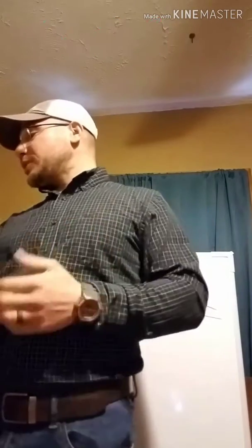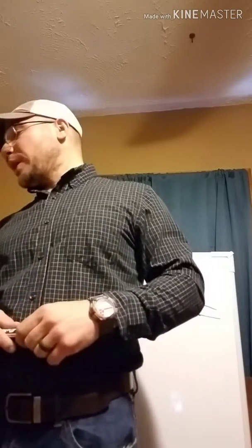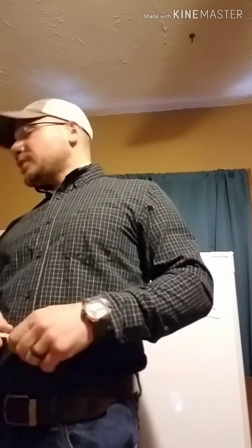Okay, so then if you look at 342.6, it's bushings. It says, where a conduit enters a box, fitting, or other enclosure, a bushing shall be provided to protect the wires from abrasion unless the box, fitting, or enclosure is designed to provide such protection.